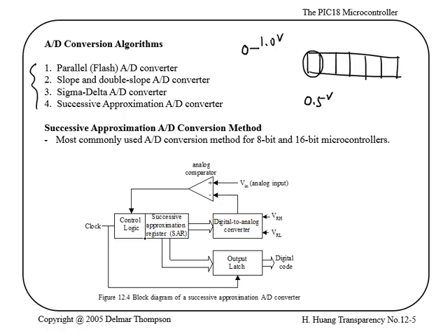So the successive approximation registers basically operate bit by bit. It says, let's take the analog input, compare it to some pre-specified 0.5 volt value, and ask, is the Vin greater or less than this? If it's greater, then you put a 1 here, and then do a subtraction of Vin minus this 0.5 volt, and then ask the question, is the result going to be 0.25 volts or greater?